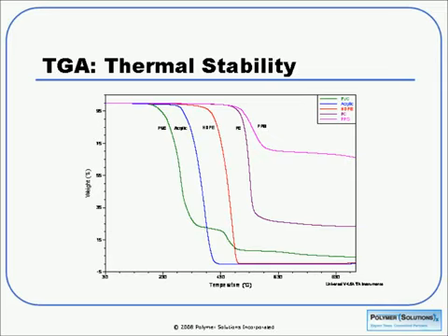So what does it tell us? Well, the most obvious thing is thermal stability because, of course, that's related to the mass loss. But we can also get an idea of compositional analysis on filler content. We use this instrument in some cases to prep samples for other techniques. Using different heating rates, we can get an idea of the kinetics of degradation of samples. And as with the DSC that we discussed, the results can often be heating rate dependent. So that's, again, something to be aware of.